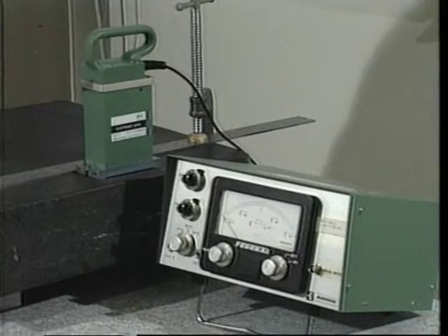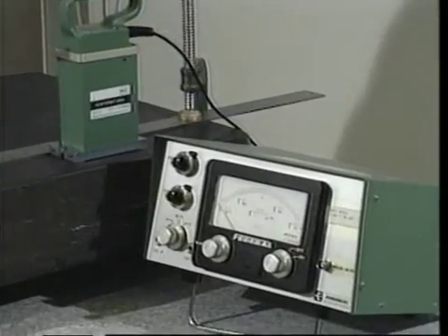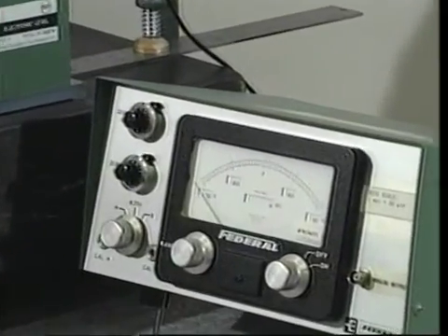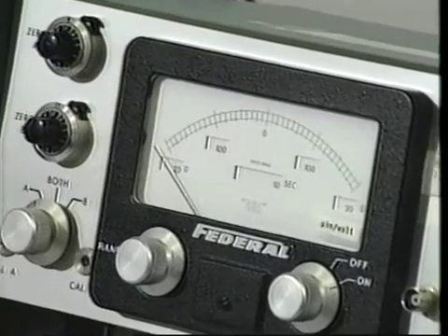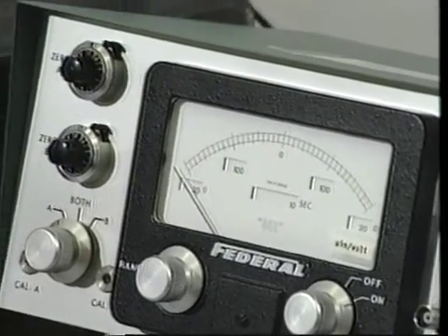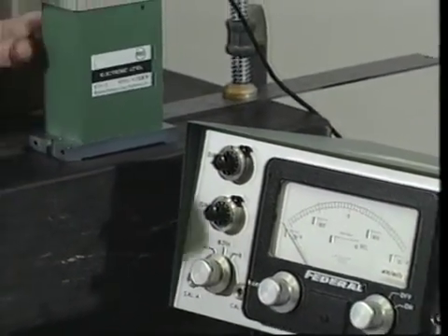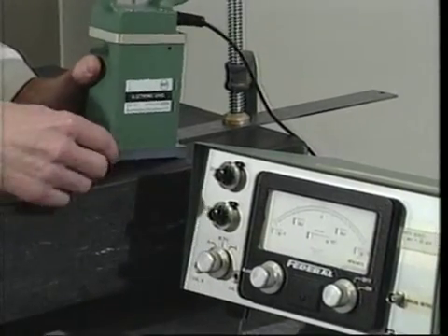While differential level operation does compensate for changes in the general tilt of the surface being measured, it does nothing to compensate for deflections of the surface during the measurement procedure. Therefore, it is most important to remember that the surface being measured must be rigid. Since the operation of the level involves a pendulum which tries to remain vertical despite the orientation of the housing, the general tilt in the surface can sometimes exceed the level's limits of measurement. In those situations, a shim can be placed under the level's lower foot to bring the reading into the range of the system.